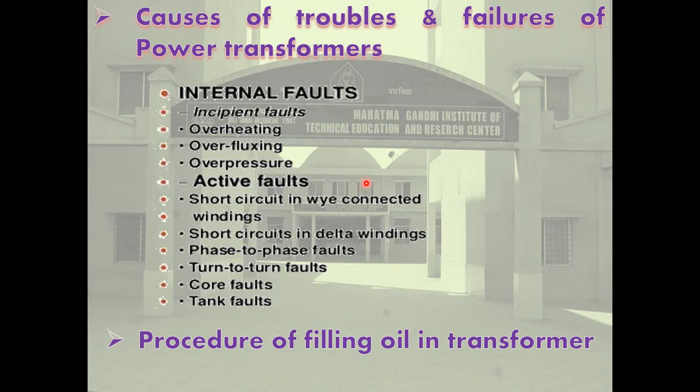Here, overheating. Now, what is overheating? Overheating caused by overload is failure of cooling systems, high ambient temperature. If overload occurs, they check cooling systems of the transformer. If failure of cooling systems, reduce load on the transformers.